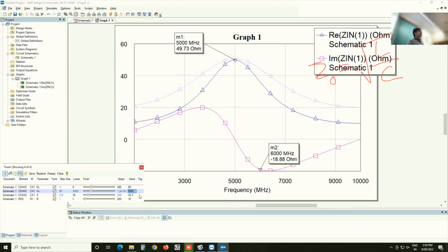And in fact, in Pozar, there is a discussion on this, that you can actually find an analytical form for the curve of how Z naught should change from one end to the other end to get a nice match. These are concepts you're familiar with if you have studied them in electromagnetic waveguides. A smoothly changing waveguide will ensure that the waves don't reflect.